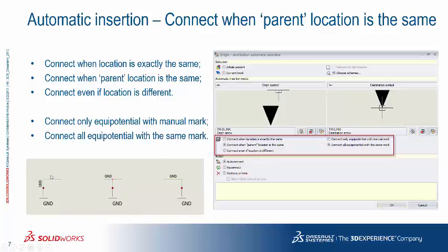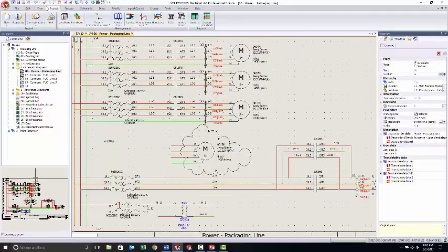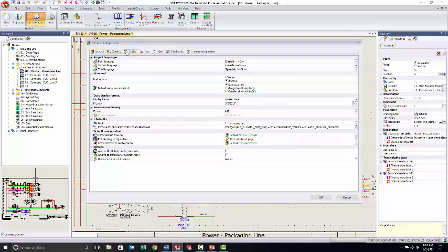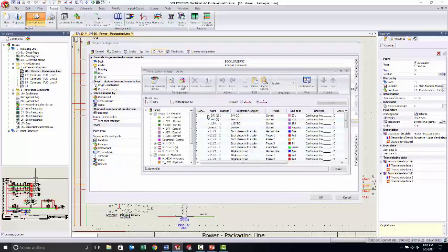But yeah, same type of thing here. If you've got wire numbers, like when you are creating your formula, and in a project you are looking at that one wire number, so we'll create a new wire style here. Let's go into the marks, into the wire style, and I will just create a new style here.